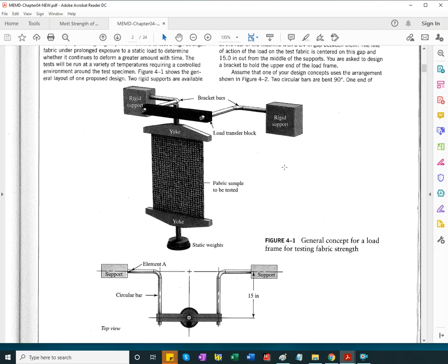So we have a combination of loads, and for an element aligned with the longitudinal direction of this portion of the bracket, one will cause tension and compression, above and below, and then there's torsion that occurs the same on the outer skin, going to zero, same as bending actually, to zero at the neutral axis.